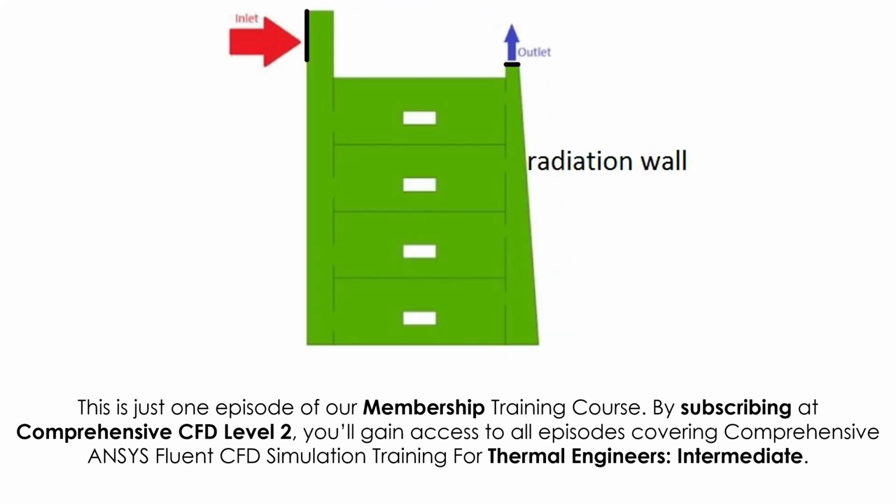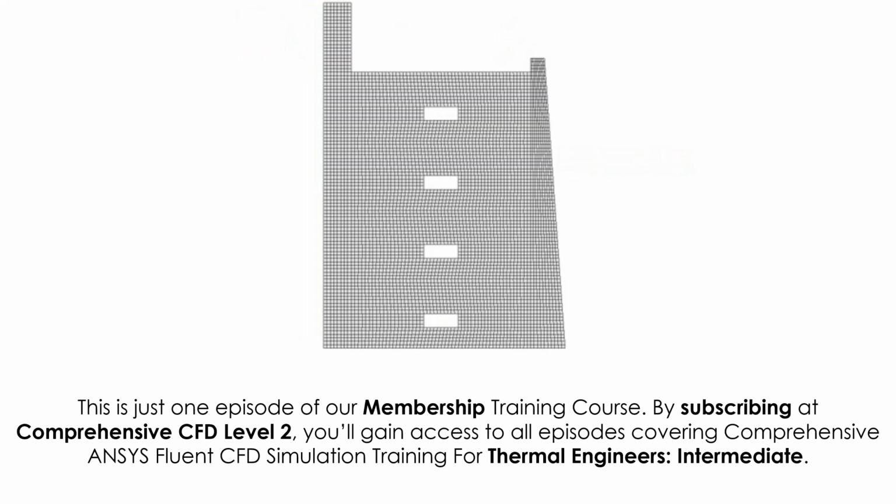The present geometry is designed in ANSYS Design Modeler software and contains a four-story building, an inlet, an outlet, and a radiation wall, whose purpose is to simulate the solar radiation energy. Also, the computational grid generated for this geometry is performed using ANSYS meshing software, and the mesh type is structured. Also, the element number is equal to 6375.